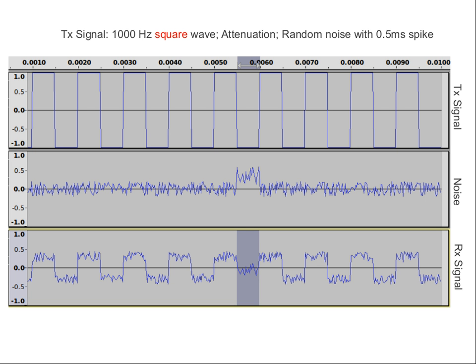Even with noise, we'd expect that what's received is not exactly +1, it may vary. So what the receiver says is, anything that is closest to +1 is considered bit 0. The closest to -1 is considered bit 1. In other words, anything between -1 and 0 is negative, bit 1; positive, bit 0. That's the scheme that the receiver uses.